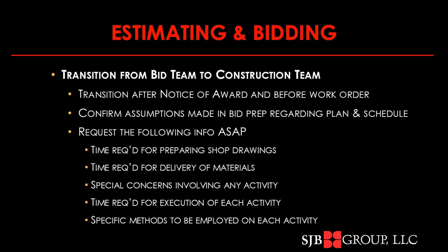And you're going to need to help out the construction team with the time required for preparing the shop drawings, the time required for the delivery of the various types of materials, and convey any special concerns that you as estimator have regarding an activity, and provide the time required for doing each activity. You want to communicate the specific methods that were used to prepare the estimate to help the construction team as they pull together their plan for the work.